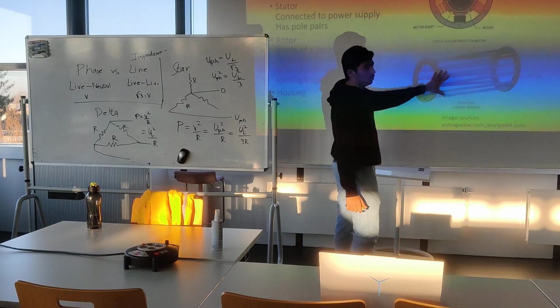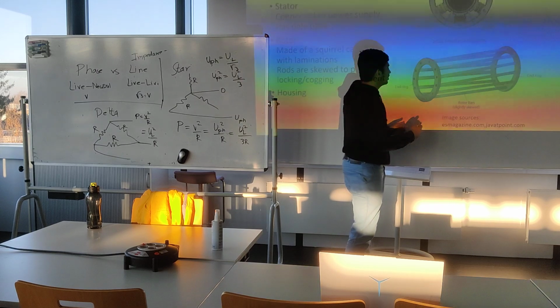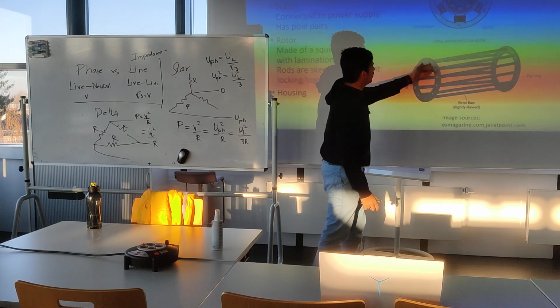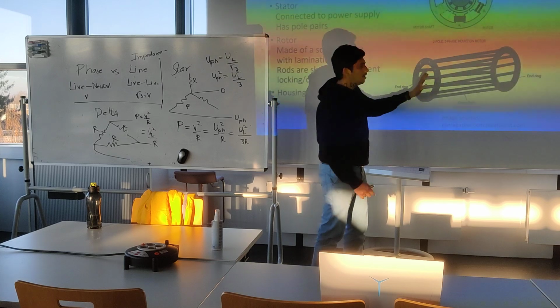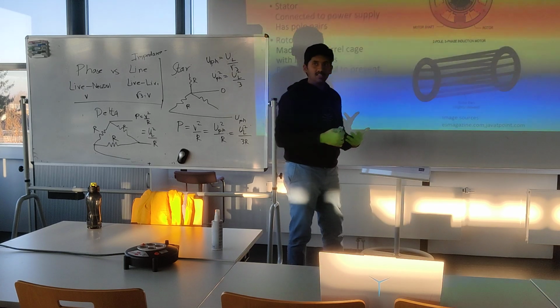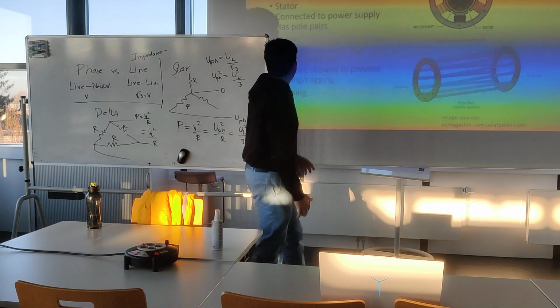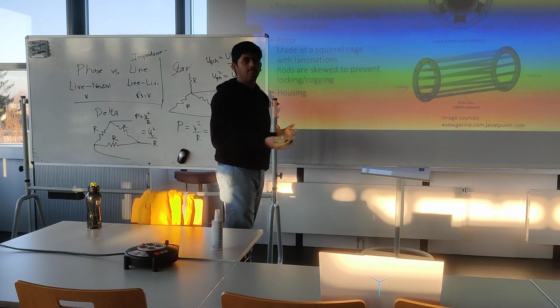So this is the core, which is rotating. But to strengthen the magnetic field, what we do is we have aluminum or steel sheets which can fit in these gaps made by the rods, and we fill this gap with many sheets, and that strengthens the magnetic field and improves the torque being produced. The rods are skewed so that the self-starting properties are better.